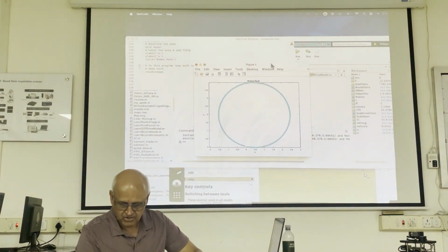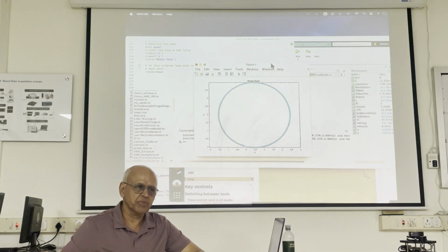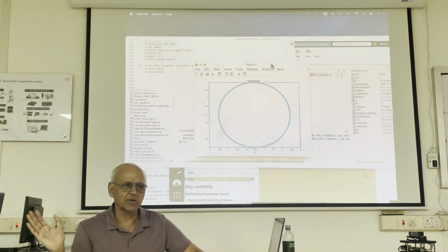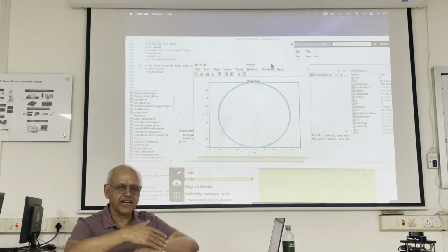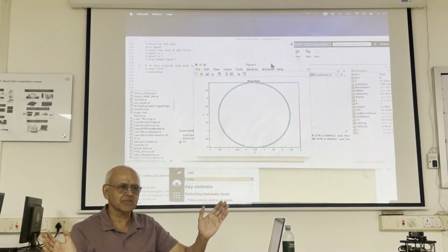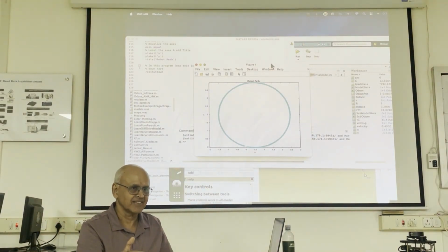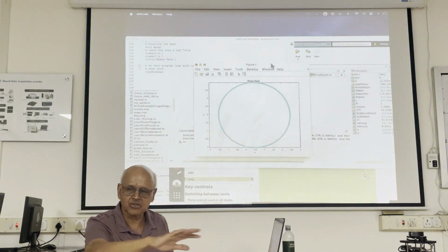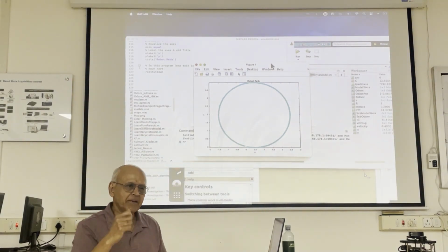So every square, you're sampling the space around that, above. So after a while, if you don't see it, you remove the obstacle. Otherwise, you'll create a map filled with obstacles, ghost obstacles. Because moving obstacles are not permanent obstacles. So you'll create a map with ghost obstacles. So mapping is a sampling operation.